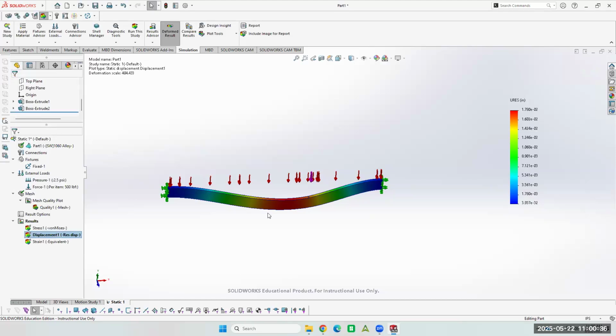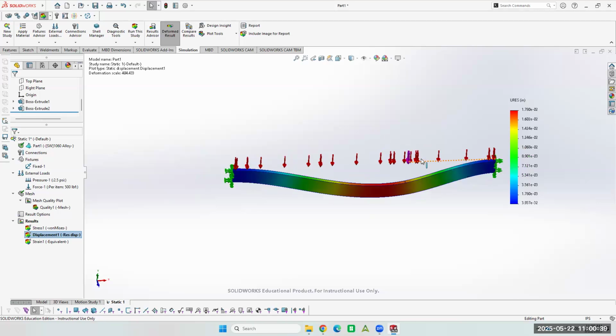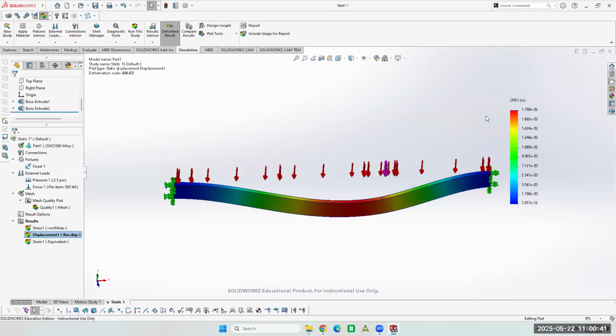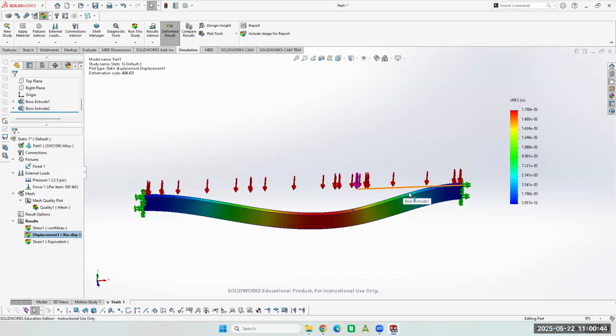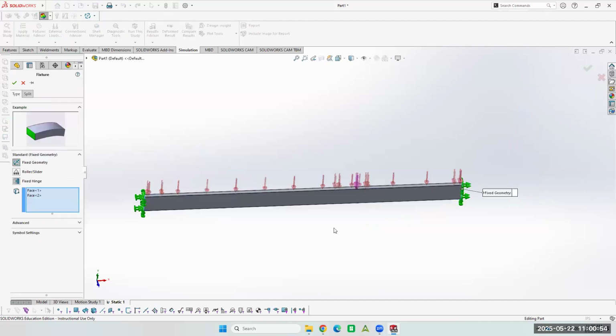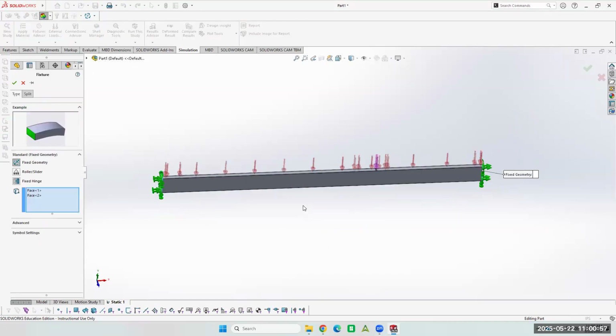What you'll find, Alex, is most of the time we'll calc it by hand, and then we'll also use the software to check it. So that's just repetition. And if it's a critical part, that's important. What's more trusted, the math or the simulator? If you want confidence to go up in your design, you want those to match. You want two different systems to match at least. And it'd be great if two different systems from two different people match. Then your confidence goes way up.